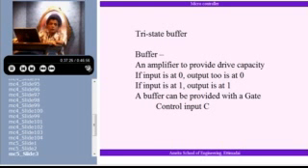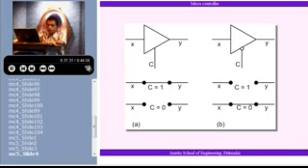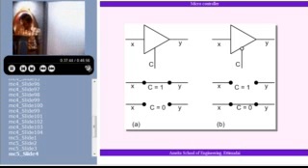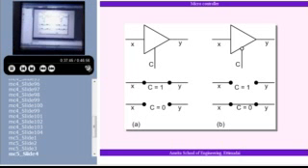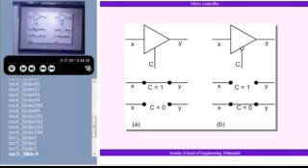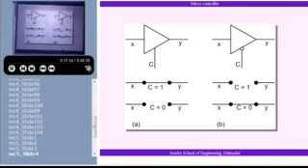Wherever you put a buffer, you have a choice. You can provide the buffer with a control signal. I have shown here a buffer with a control signal. This is a buffer with X as input. Y is the output. Whatever be the value of X, it will be reproduced here. C is the control signal. If C is 1, the buffer is on. There is a link between the two. Input is connected to the output. If C is 0, the connection is snapped. The buffer is off.